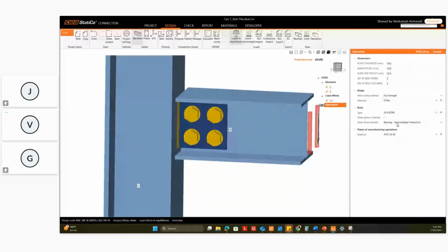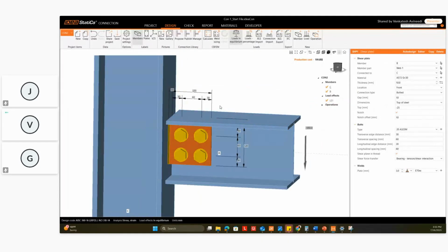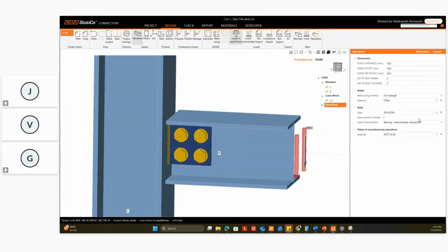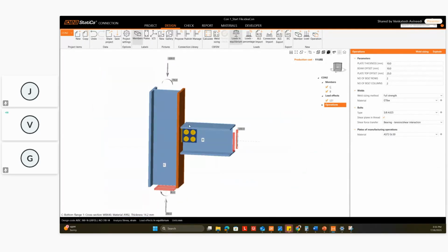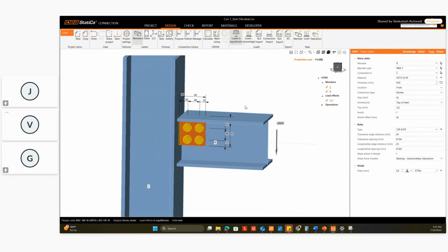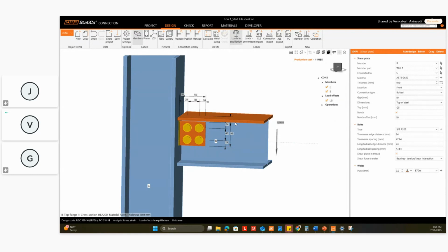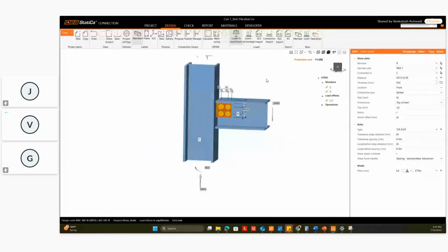so 20 dia is different, 60/30, and for any other bolts it is different because we gave expressions to calculate and automatically make those changes in the model. So this is how you can easily play with parametric templates to get the most out of it.